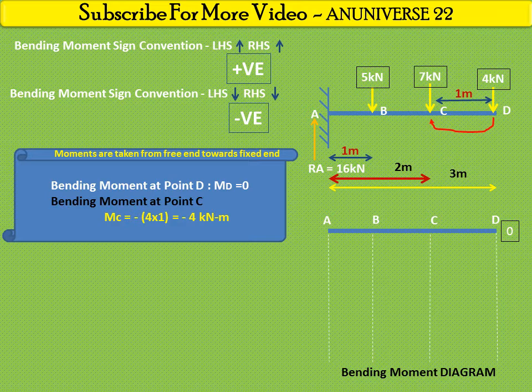We take the negative sign because the load is acting in the downward direction. In the bending moment diagram, we start from point D at 0 and move to 4 kilonewton meter. We draw this line below the baseline, which means these are negative values.